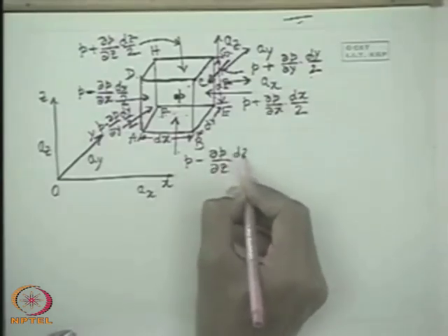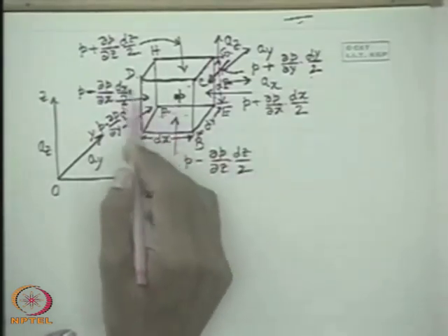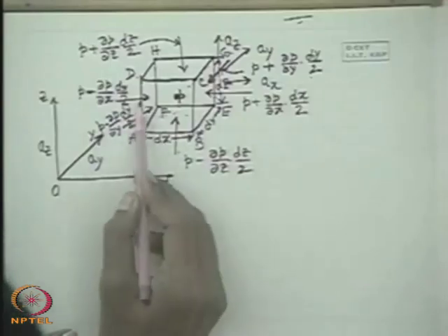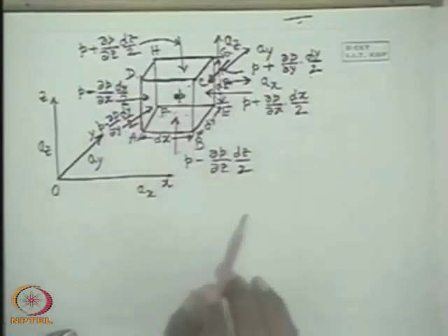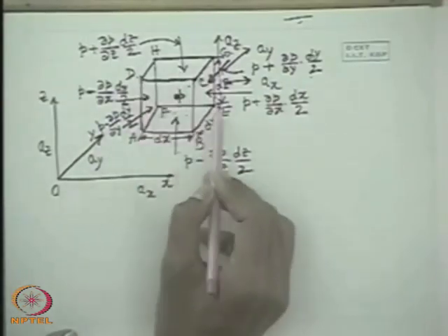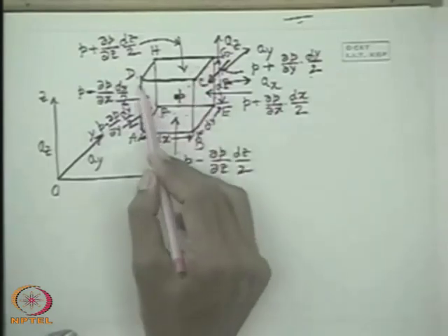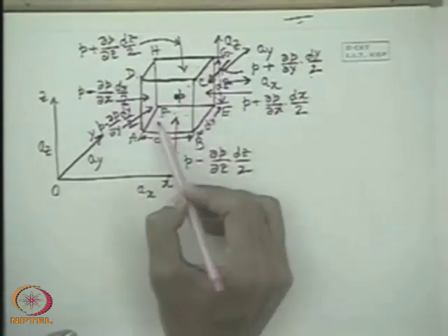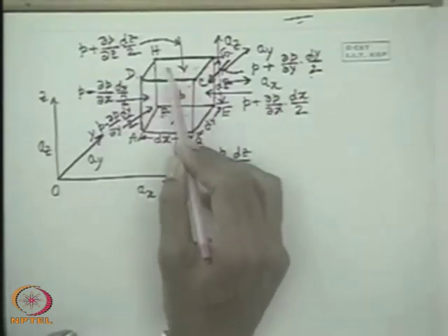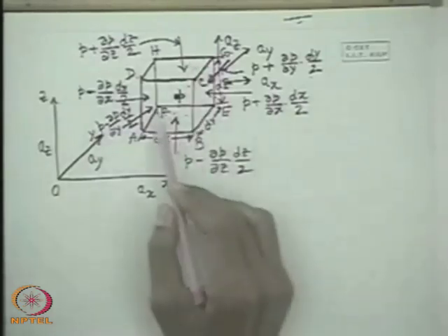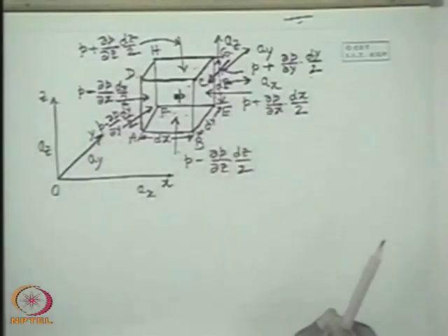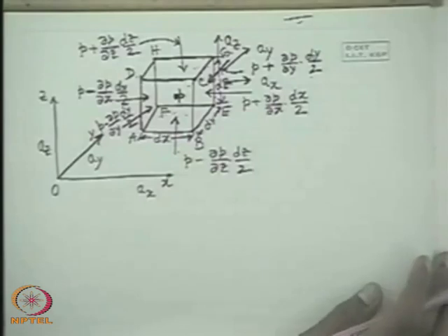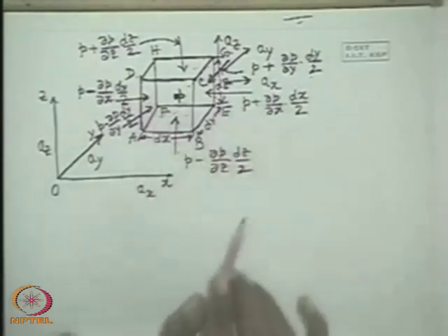That means with respect to a pressure P defined at the center of the parallelepiped, we can specify the pressure at each face. That means 2 x faces, faces perpendicular to the x direction, 2 y faces, faces perpendicular to the y direction, and 2 z faces. So for the 6 faces the pressures are specified like this. Now simply we find out the force balance equation.